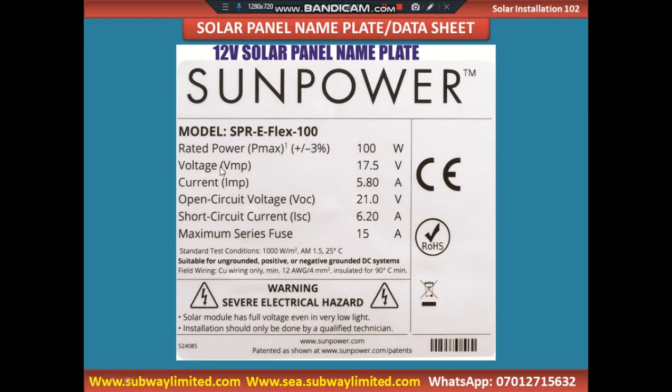And the voltage at maximum power: we said that to have the maximum power, you always have a voltage at maximum power and a current at maximum power. You can see here that this voltage at maximum power is less than the open circuit voltage. If you multiply voltage at maximum power by current at maximum power, it is certainly going to give you something close to 100 watts.